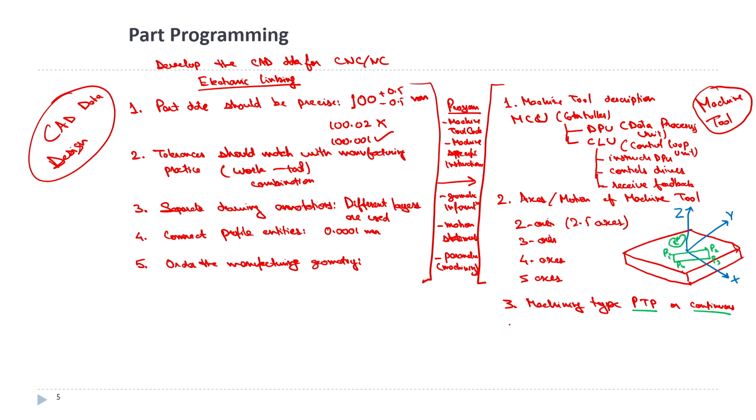Also, it is important to understand that there are 3 kinds of systems in the machine tool. It could be a numerical control, a computer numerical control, or a distributed numerical control. Numerical control, as I just discussed, is a machine where the program is stored on a CD or in a system other than a regular computer.